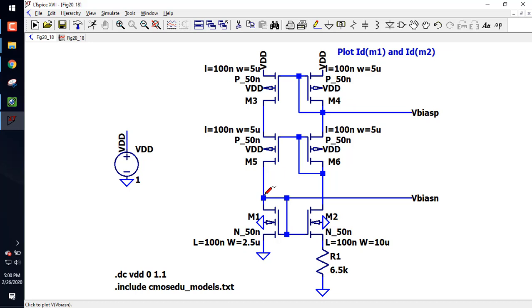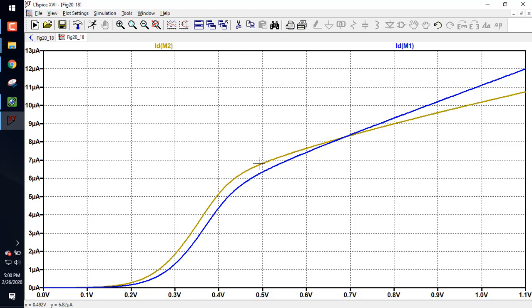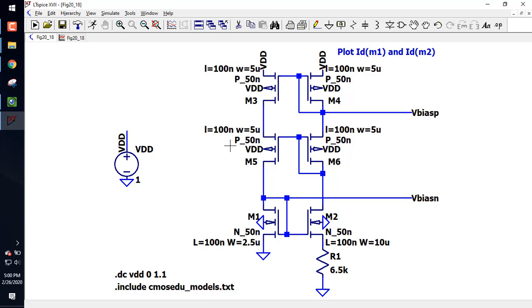Now, before we go any further, I want you also to estimate the minimum VDD, because before, our minimum VDD was like, I don't know, guess like 0.4 volts or so, 0.5. What's going to happen here? I need to have a VGS here, which is 0.35, a VGS here, which is 0.35, or 0.7. And then if I go here, this is 0.7, I need to have a VDS sat, say 0.05. So I'm going to be almost at a volt, like 800 millivolts, before this turns on.